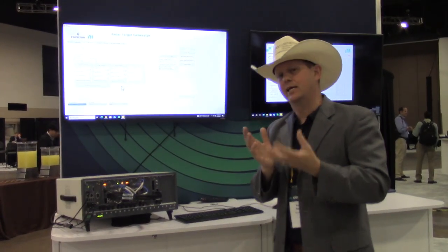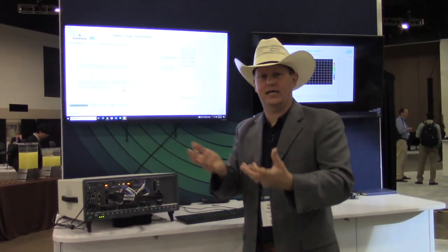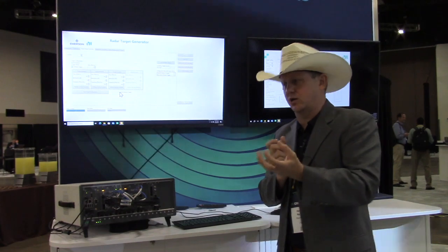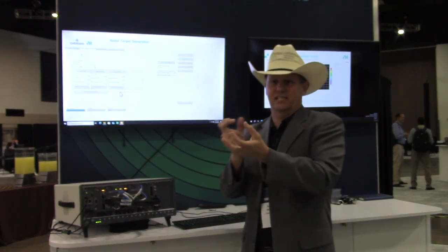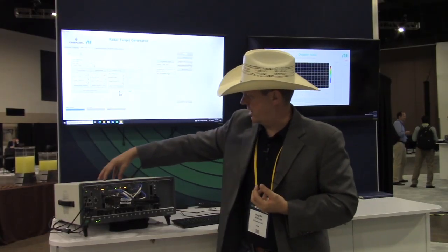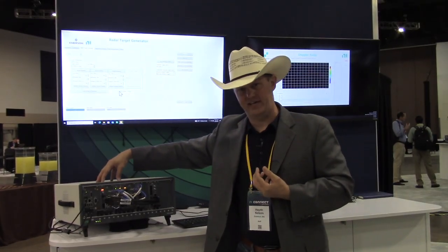That's a really unique test use case, because if I'm testing a microwave radar, I may want to test it with really clean targets and then also with targets amidst things that are not supposed to be there, or clutter, or things of this nature. And so here I can emulate all that with this second VST.